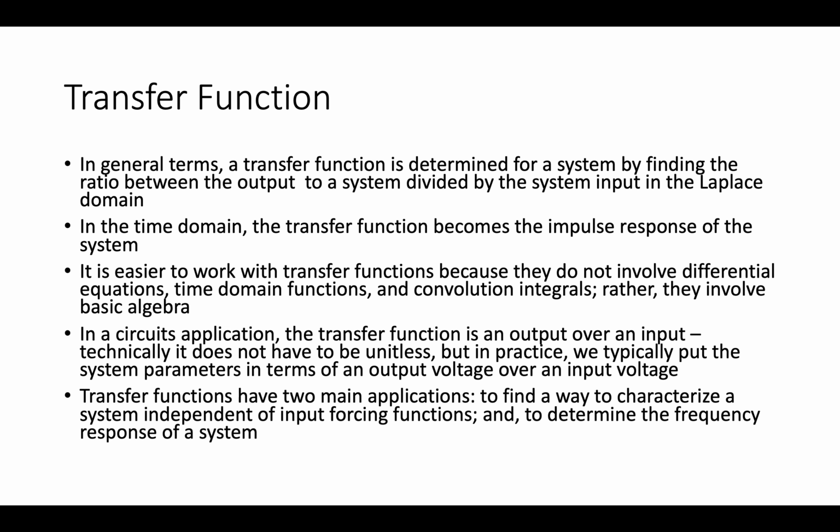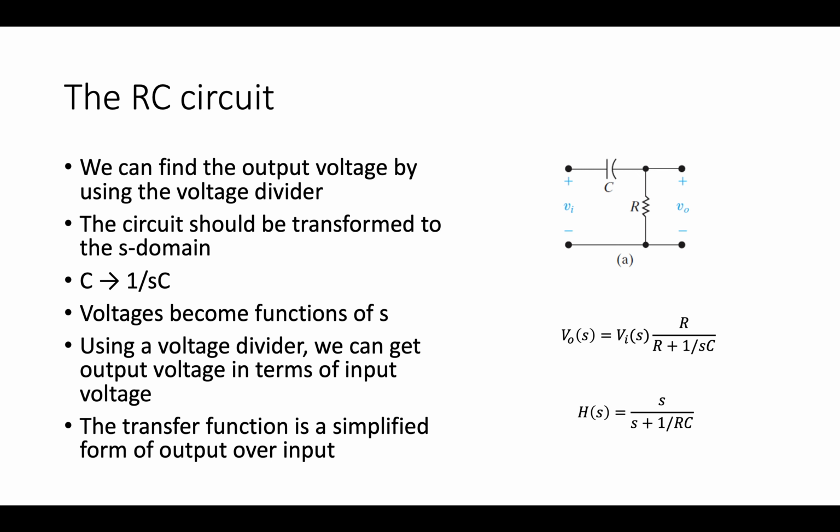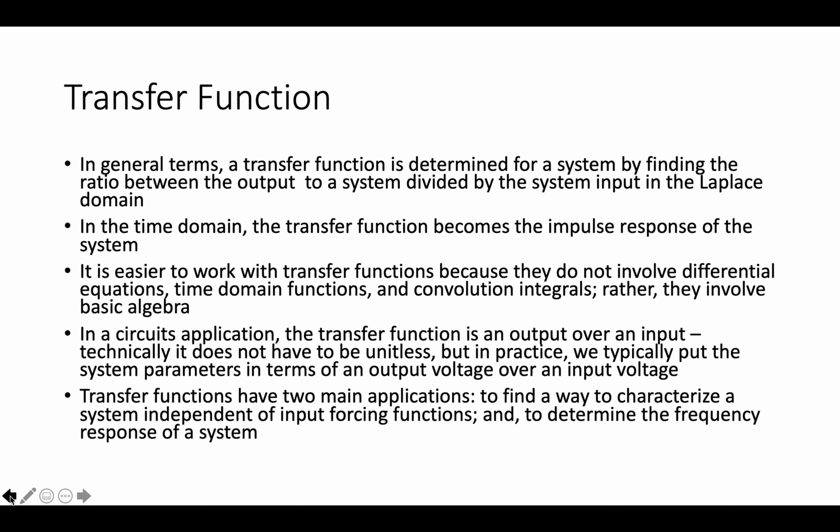So in a circuits application, the transfer function is an output over an input. Technically, it doesn't have to be unitless, but in practice, we almost always put the system parameters in terms of an output voltage over an input voltage. The transfer functions have two main applications. First, to find a way to characterize a system that is independent of any input forcing functions. And secondly, to determine the frequency response of a system.